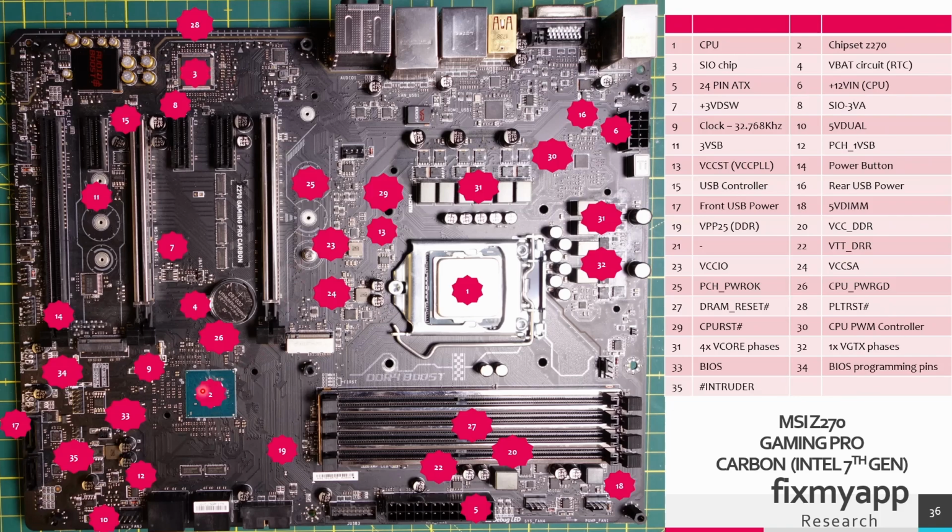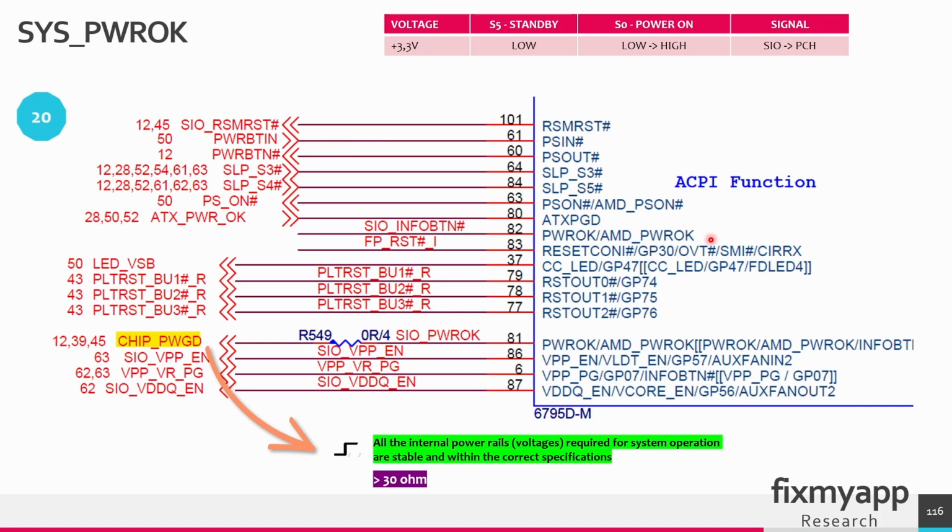In power sequence 20, the SuperIO chip received the ATX power OK signal from the PSU, saying that all the power on voltages are OK. After that, the SuperIO chip will send a chip power good, also known as a system power OK or power OK signal, back to the PCH. And this signal goes from low to high. The resistance of this power OK signal is higher than 30 ohms. The power OK signal can be called system power OK, or chip power good, SuperIO power OK, or just power OK.